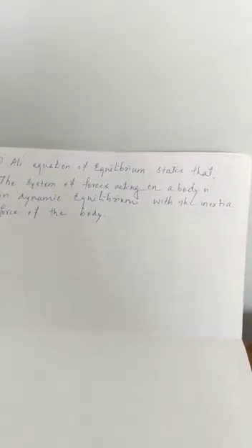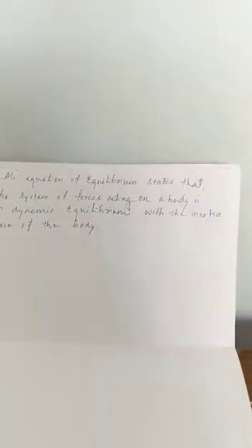When the lift is moving up, the net resultant of the forces, that is the force pulling it up and the weight acting downward, will act in the upward direction. That's why the lift is moving up. But in addition to that, it has to overcome the inertia force, which will act in the downward direction. This creates a dynamic equilibrium of the lift.